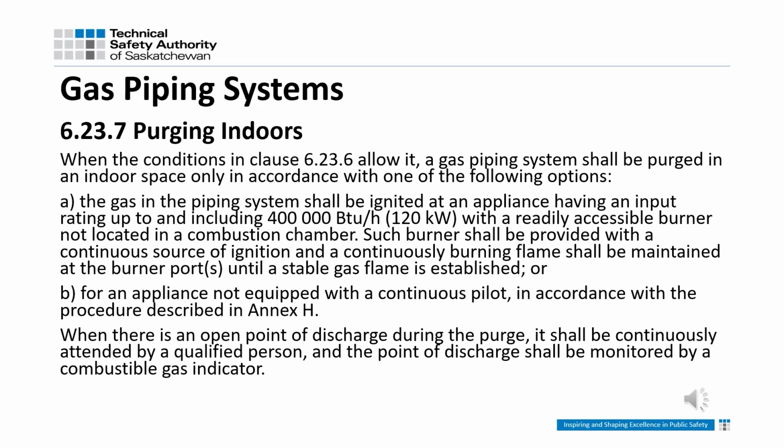6.23.7, Purging indoors, has not changed except the language is clearer. And the last sentence, where there is an open point of discharge during the purge, it shall be continuously attended by a qualified person with a combustible gas indicator.